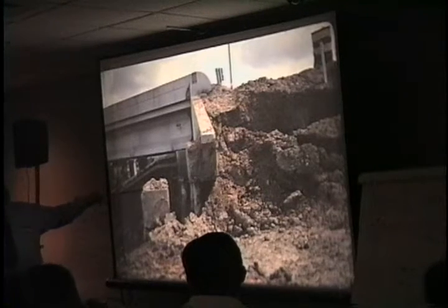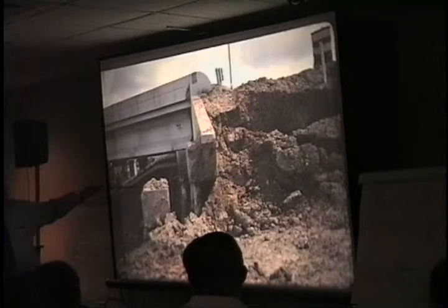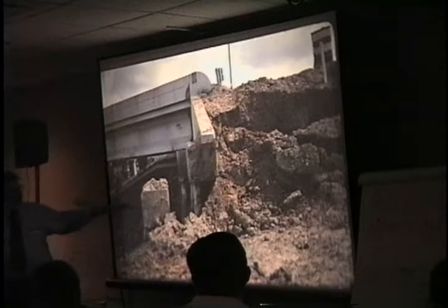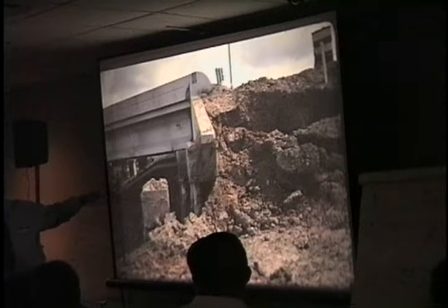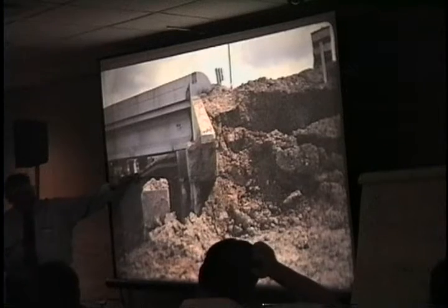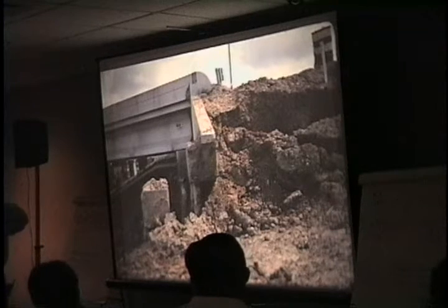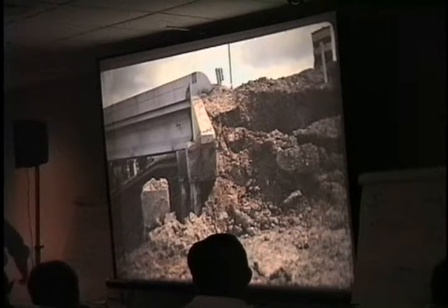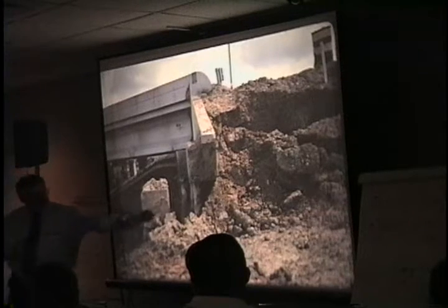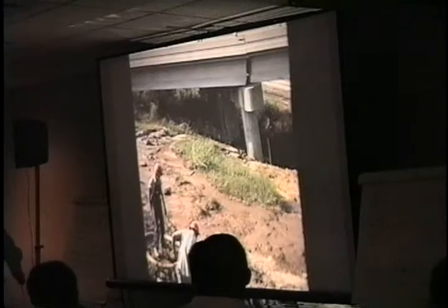Okay, I've seen this rarely. These are steel piles that have been capped in groups. This is not done much anymore. They used to cap a few piles and they would just set the girders on there. Now I would design it as one continuous girder or grade beam over the top of the piles and make sure it's well reinforced. But the story here is it moved laterally. It could be a shallow or deep slide.